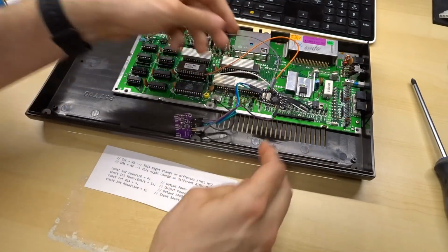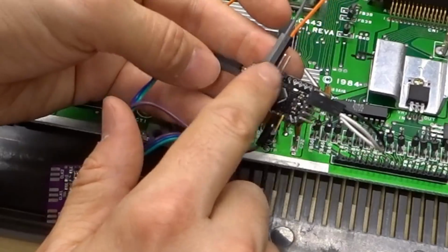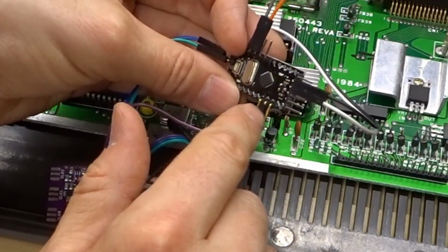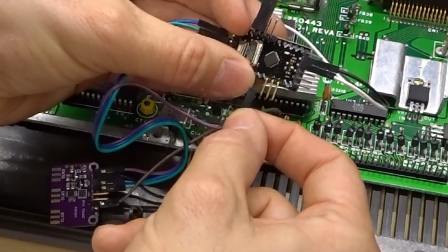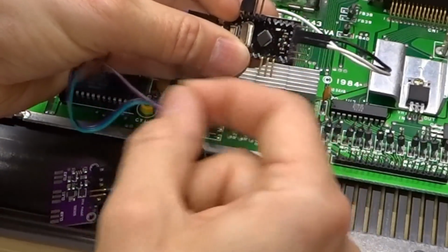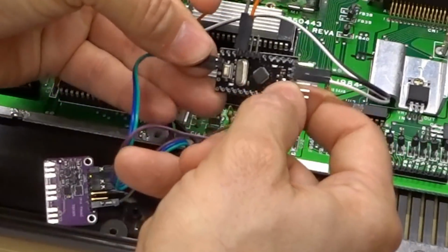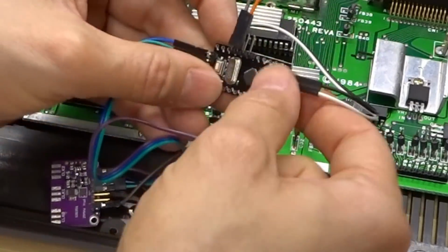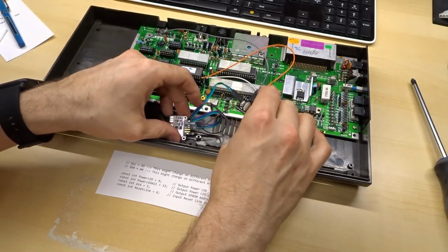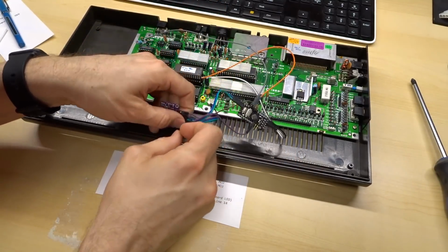Okay, so at that point, other than the power LED, everything is connected. Let me just quickly double check all the connections. Alright, so I see this is ground, this is reset, where I have this purple wire, which is wrong, because this is VCC to the little clock synthesizer. That's the VCC. This particular Arduino, it's a little hard to see once you solder the pin headers on. It kind of covers up the labels. So there we go. So I'm going to stick these down, but I'm going to just test this out first, make sure everything is working.